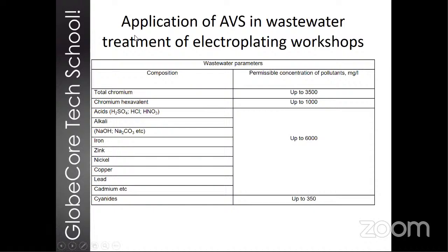And when removing copper from wastewater, it's important that there is no bismuth or ammonia in that water because those lead to the formation of water-soluble copper compounds that are much more difficult to deal with.